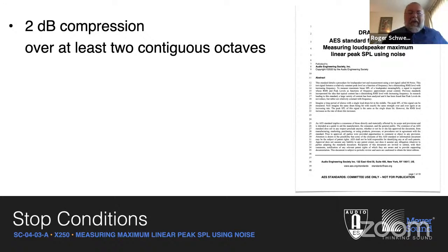Well, we did quite a lot of testing internally before we released M-Noise in the procedure, and we found that, in order to reproduce it consistently, we literally left the speaker and the procedure in a room and had different people come in and measure it. In order to reliably get the same maximum SPL, you had to look for more than a dB of compression.